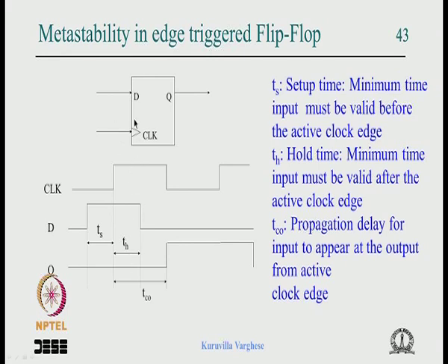Now when the clock period is enabled, the slave latch will take some time to set, and that is the propagation delay. Okay. So that is how this comes. During the negative clock period the master is in transparent mode. Before it is cut off, the latest the master can latch is the setup time, that is the cross coupled latch delay minus any inverters in the path.